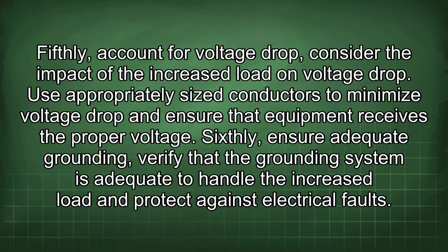Fifthly, account for voltage drop. Consider the impact of the increased load on voltage drop. Use appropriately sized conductors to minimize voltage drop and ensure that equipment receives the proper voltage.